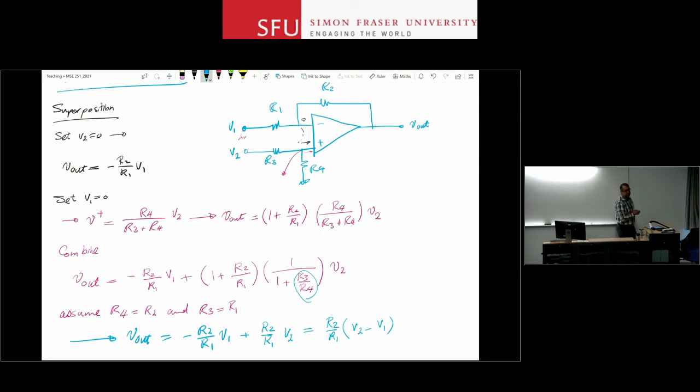And now you have a circuit that can subtract analog signals from each other. And that's great. So basically, you can now do a lot of mathematical functions. You can see multiplication, for example. If you want multiplication by a constant, you can use an OpAmp circuit and multiply a current by R2. That gives you a multiplier or a voltage gain, right? So it could be a multiplier. You have adders, you have difference amplifiers.